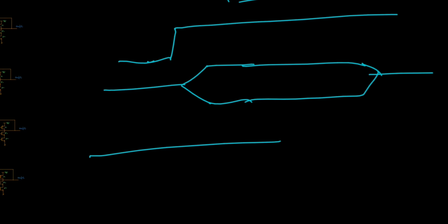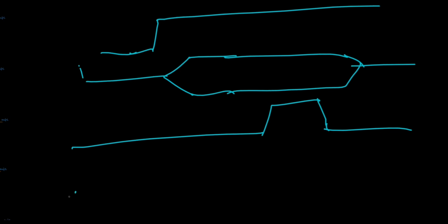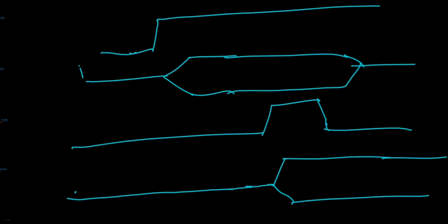The only time that I could be written on the output, imagine that the out was already 0, the only time that I could be written on the out is at this time. At this time, when clock goes to high, then we would have the out to have the input value.